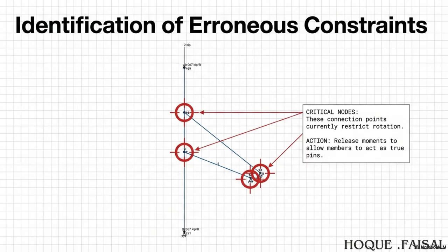You put it up, you pour the concrete, and you take it down a week later to use on the next job. You don't weld it, you pin it. You use clamps and bolts. So modeling it as a welded structure is incredibly dangerous because you are predicting a strength and stiffness that simply will not be there on the day of the pour.